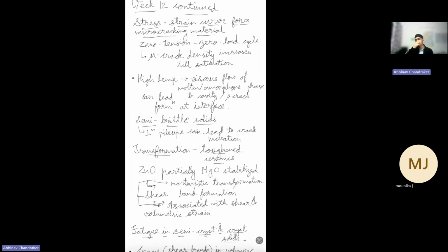So previously we had seen some summarization of fatigue, majorly the Coffin-Manson equation, Basquin equation. These are relations which are very commonly used, and these are simple relations, so they can be very easily applied to get some estimated relationships or for analyzing your fatigue test results. These are useful. And then we have Paris law, which connects your fracture mechanics to fatigue for studying fatigue crack growth phenomena.